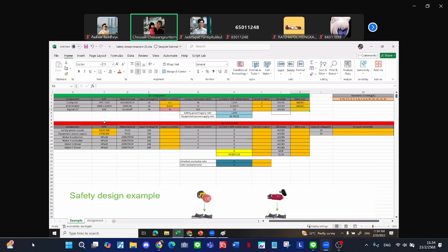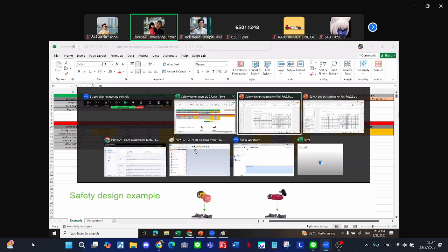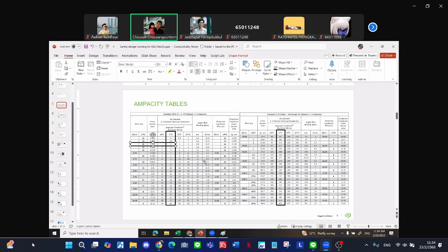And last one for the IO, I assume it's just a current of 8 ampere here, and after it calculates back, it will be multiplied with the 25% safety factors. The standard circuit breaker rating here is 10. And then use this one to select the wire size again. 10, 10, 10. 16 AWG.